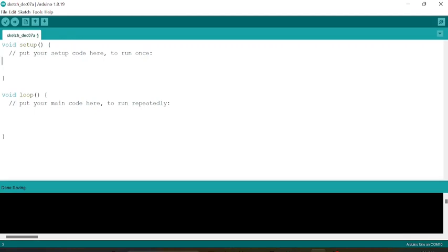So configure it using pin mode, pin 1 as an output. Then we have used pin 12 as the input pin of the push button. So write pin mode pin 12 as an input. So we have configured the various pins.